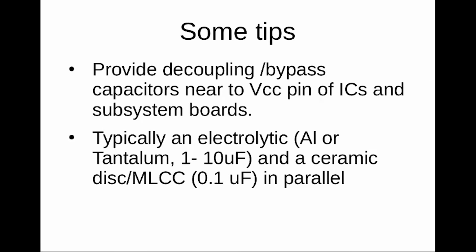The value can be 0.1 microfarad. These two different types of capacitors must be connected in parallel, and they should be physically placed very near to the supply voltage pins.